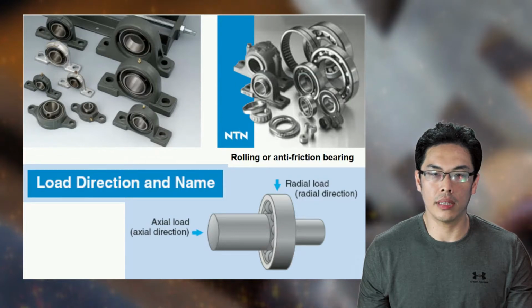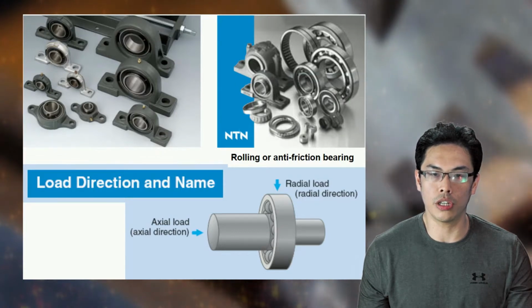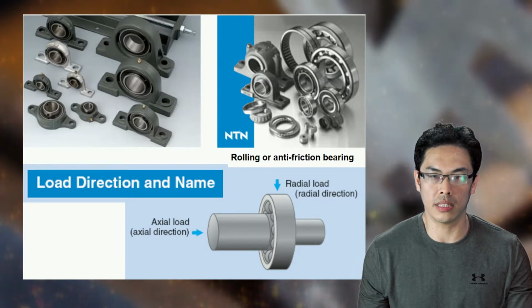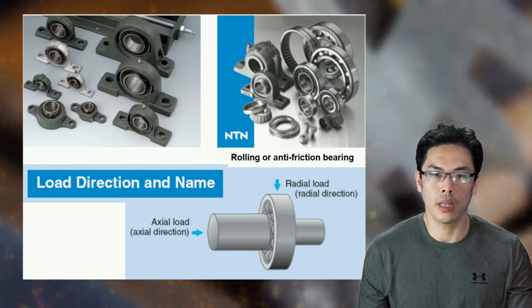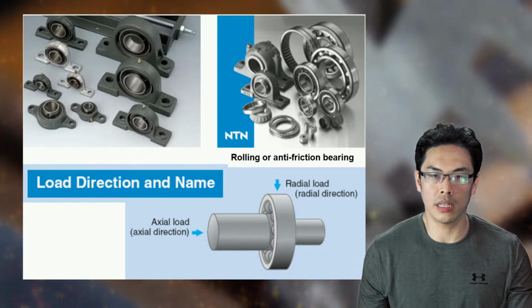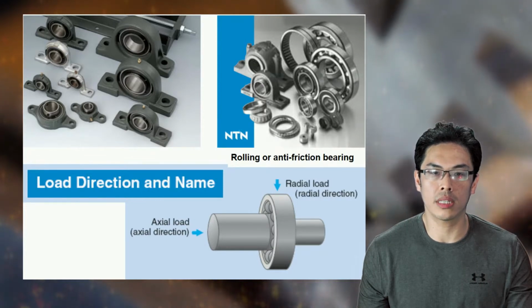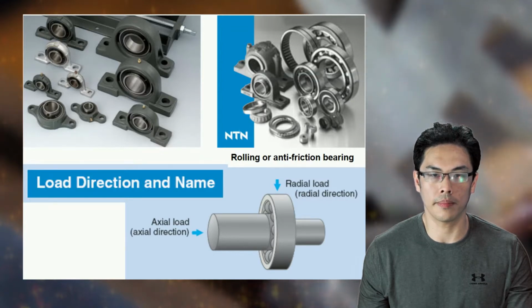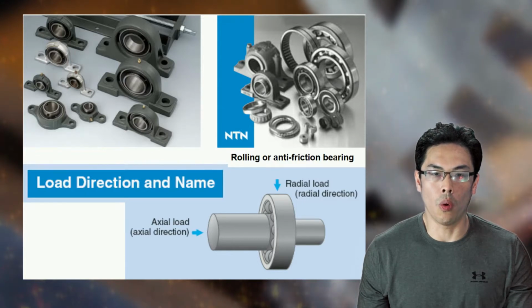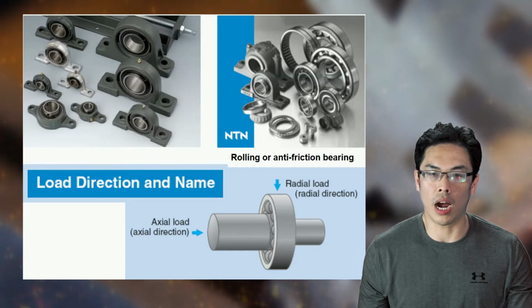In plain bearing, the starting resistance is much larger than the running resistance due to absence of oil film. In ball and roller bearings, the initial resistance to motion is only slightly more than their resistance to continuous running. Hence, ball and roller bearings are more suitable for drives subject to frequent starting and stopping as they save power.